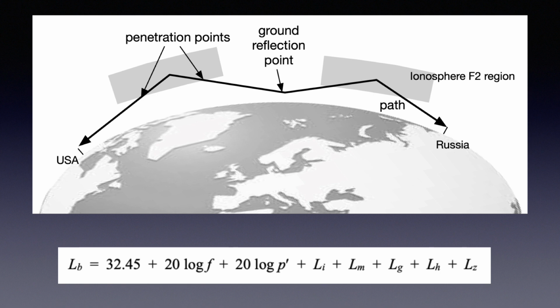Making a prediction is a matter of using a computer tool. Any HF Skywave prediction tool must embrace the decibels defined in each of the terms described here, then inserted between the transmitter effective radiated power and the real receiver threshold in a path budget.